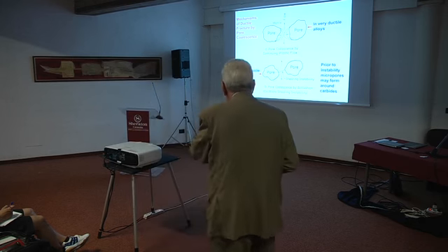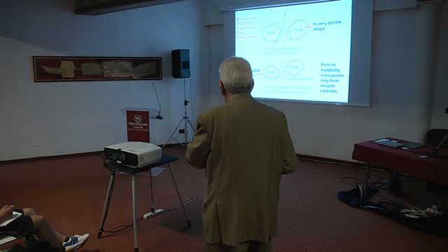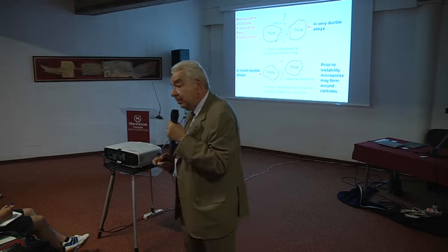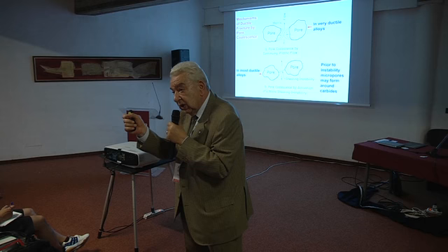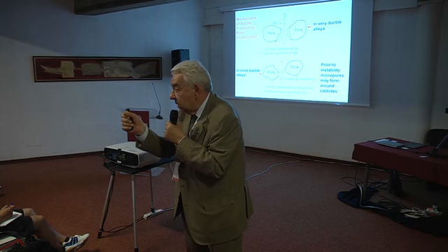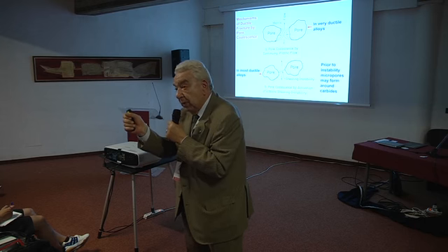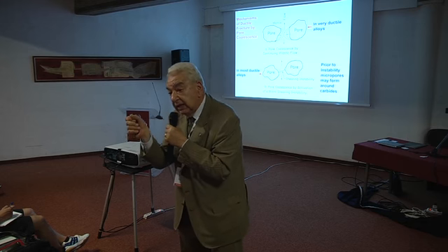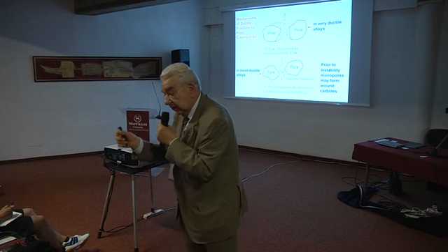And by continuing plastic flow, the ligament reduces its size more and more, up to the point that there is no more a ligament, there is no material that is resisting.